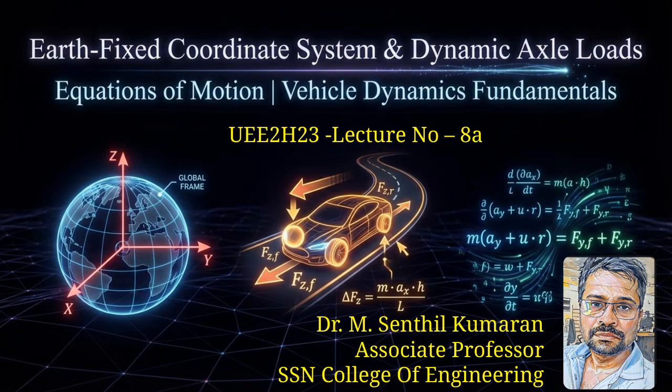Good morning, everyone. Today we move deeper into vehicle dynamics. Specifically, we will understand the Earth fixed coordinate system, dynamic axle loads, and how to formulate the vehicle equations of motion. Whenever a vehicle accelerates, brakes, or corners, forces and moments shift between the axles. Understanding this weight transfer is fundamental to predicting handling, stability, steering feel, and even crash performance.